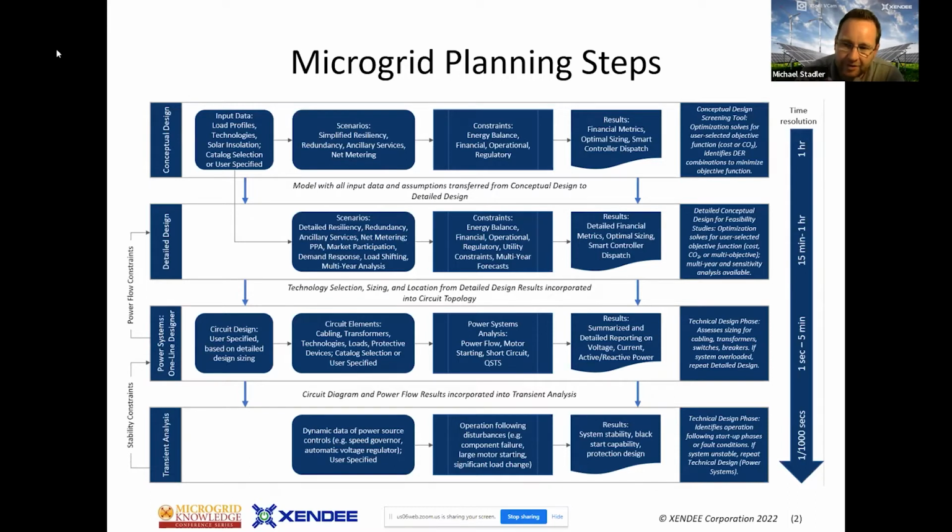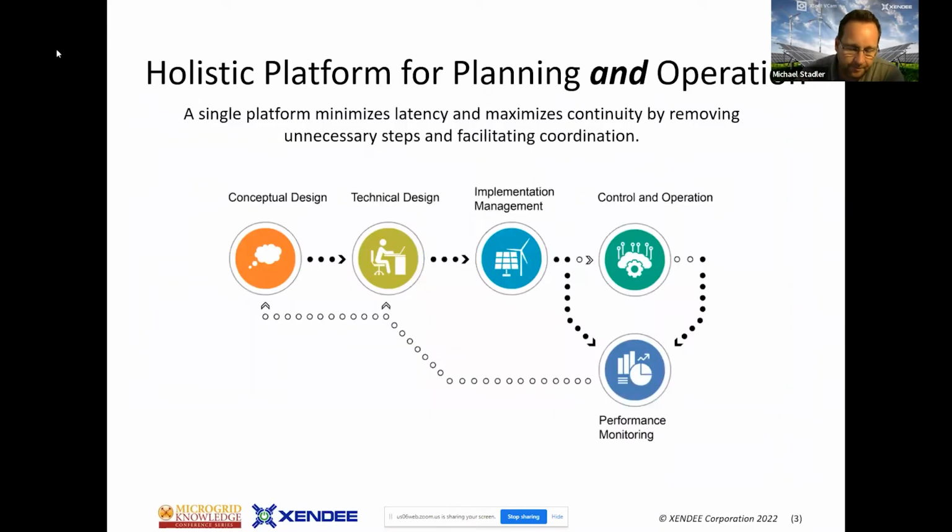And then when you have all this defined, you go very deep into power system one-line diagram design, where you think about motor starting, short circuit analysis, and also transient analysis. Our platform doesn't provide transient analysis for the clients. We do this internally. But transient analysis is really a very complicated field, and we decided that if someone needs it, we can help you with it. But at this point, we are not settled on how we will bring this into the platform.